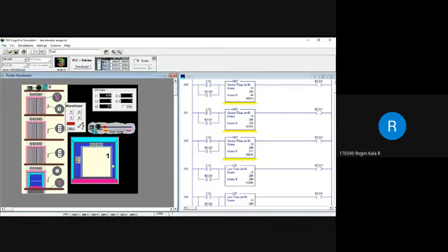Now consider initially that the lift is in the first floor. So here you see I:1/4. If you want to move from the first floor to the fourth floor, we use the greater than symbol, where A denotes the first floor. For the first floor, the decimal value is 296, so it compares whether 296 is greater than 44. 44 is the value of the input floor, and source A denotes the lift at its present position. So it checks that 296 is greater than 44.